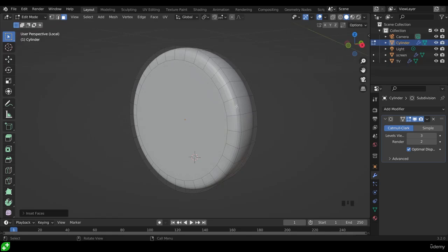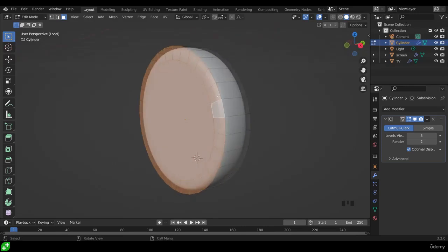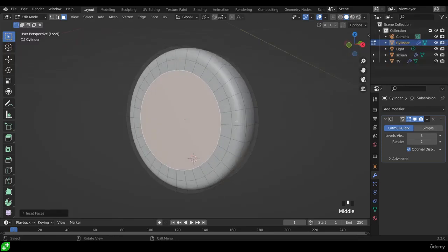The reason it's now keeping its structure more is because this face at the front and the faces around it are planar, so they're flat, as you can see around there. So it's using the quads from here for the curve, but this section it doesn't need to worry about so much. I could smooth this out even more by doing another inset here, and can you see how it's lost that slight wobble around here, and it slowly smooths out a bit better.